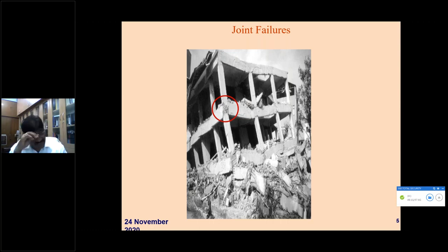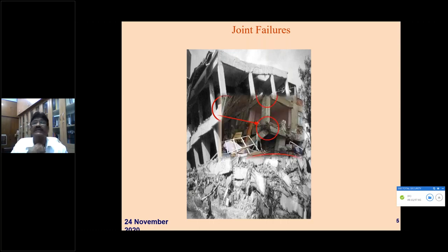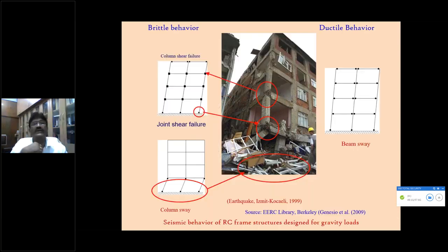Now, carefully observe this diagram. It's very, very important for us to look into that. All the existing buildings were designed based on gravity loads. That means we have the dead loads and the live loads, assumed to act in the downward direction, and the distribution of bending moments and shear forces due to gravity loads is something different. All these buildings were designed based on the gravity load design approach. It's fine: beams are normally stronger, and columns are okay, as per the moments and shear forces acting.